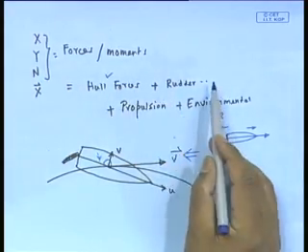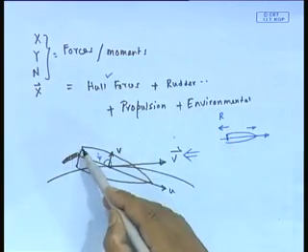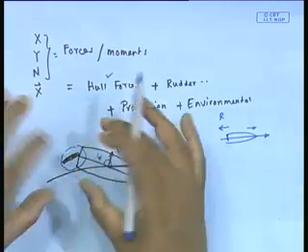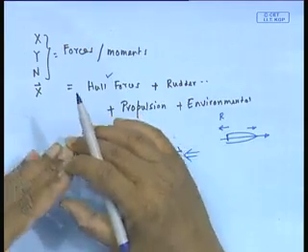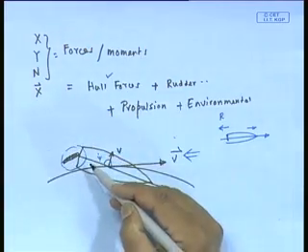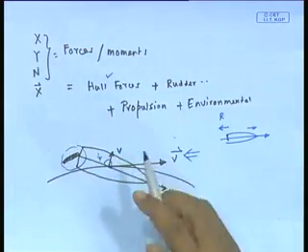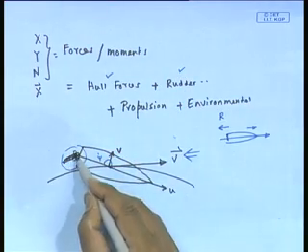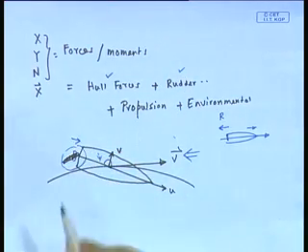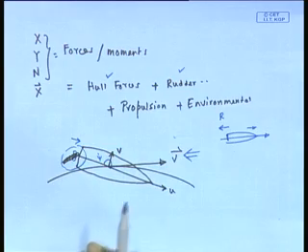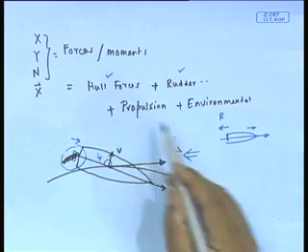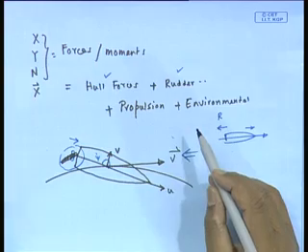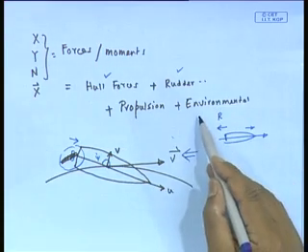Now, obviously, you have got this orientation because you have actually put the rudder at some angle, which has given some force. In fact, that is what has started the ship to turn. So, that is rudder forces. Now, propulsion force: because I have a propeller here, the propeller is going to give me a thrust. So, that gives me propulsion forces. And if I have, for example, waves, currents, wind, etc., I can call them environmental forces.